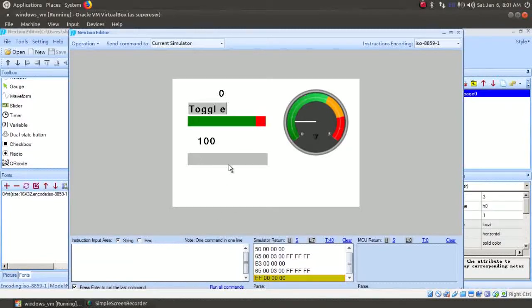Here you can see it, and this is our progress bar. And we can actually play around with a few things here. For example, if we want to update the contents of this display, this label, we can just simply call t0.txt equals, say we want to say 5.25 for no reason, and actually we made a mistake because it's a string, obviously. If we press enter now, it shows the value.